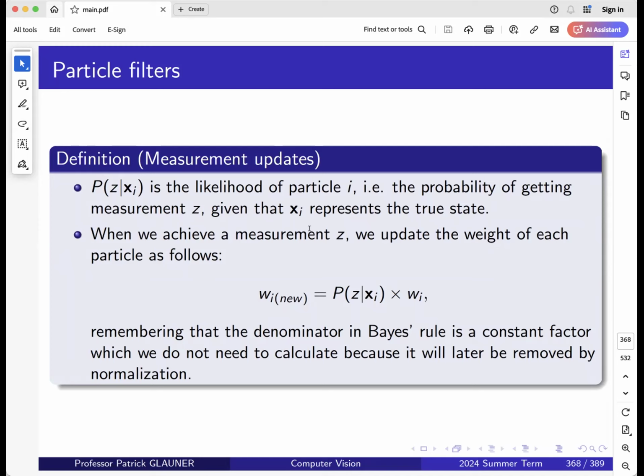and you could use a deep neural network for depth estimation. And your depth measurement can be a measurement from a sonar, but you could also have this depth estimation from a neural network, for example, or from a stereo vision approach, whatever. This would be your measurement update Z, and then you need to model how likely that measurement Z is given your particle.